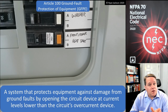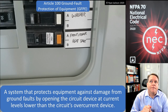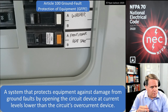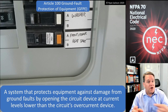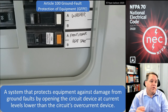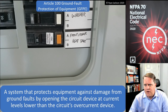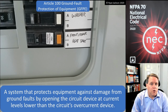So where do you need ground fault protection of equipment? Off the top of my head, you have 426.27 for heat tape, and you also have 427.27, which is for pipe trace heating, which is kind of similar in concept to heat tape. And then you've also got it for services and large breakers in 230.95, 240.15 as well, if I'm not mistaken. If it's not a service and it's a feeder, that's where you would look for the requirements for it.